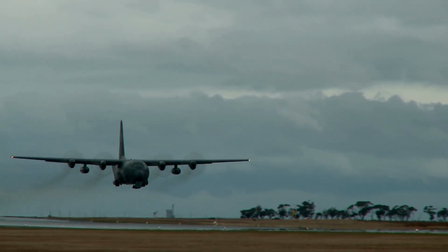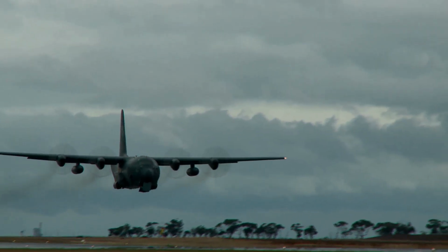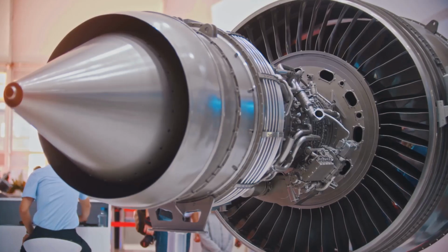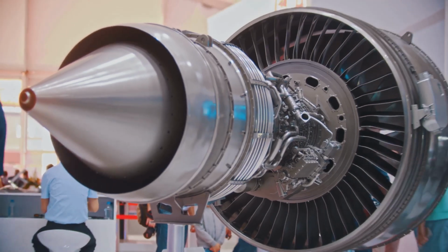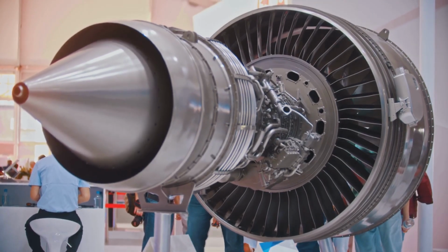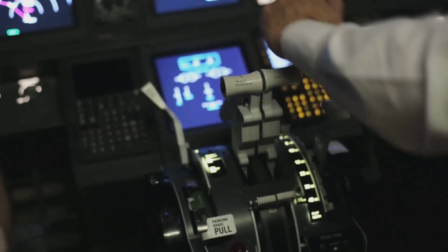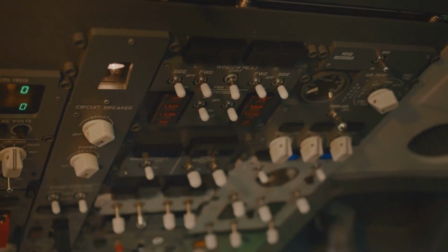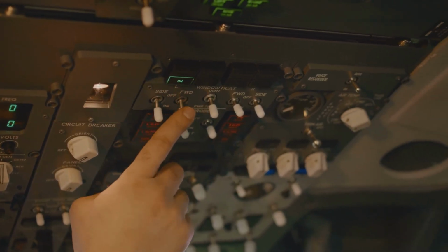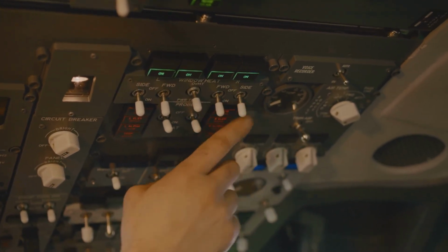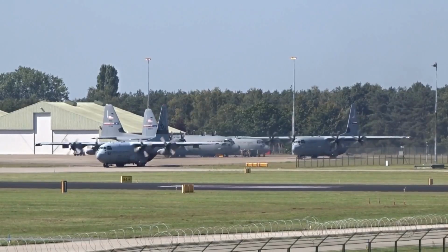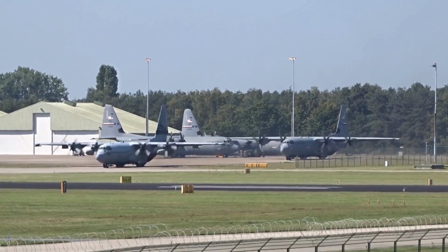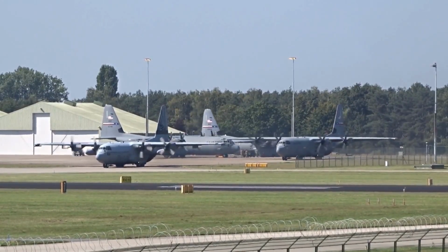New technologies designed for turboprop engine upgrades include lightweight composite materials for propellers and engine components, reducing weight and increasing durability, and the precise management of engine operation, optimizing fuel consumption and performance through full authority digital engine control, FADEC systems. Other improved systems include the hybrid electric propulsion system, which combines traditional turboprop engines with electric motors for